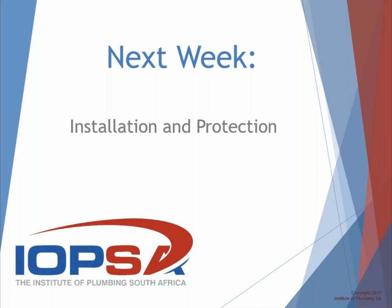Yes, it is. Around the geyser, the first meter of pipes surrounding the geyser, TP, cold in, hot out. But then it also becomes compulsory on the entire hot water reticulation. All the pipes that are exposed in a hot water reticulation system need to be lagged. This is, we're talking new builds and new homes.